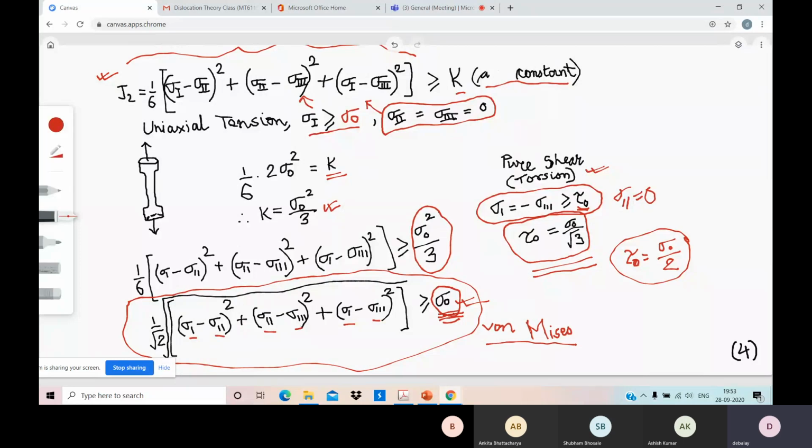This is simply continuum solid mechanics. But for design this is quite applicable, because this gives you reliable prediction. It may not be very accurate, but it will be close. If the criteria is satisfied, then you may say there is a high chance that yielding will occur because Tresca and von Mises both are satisfied.